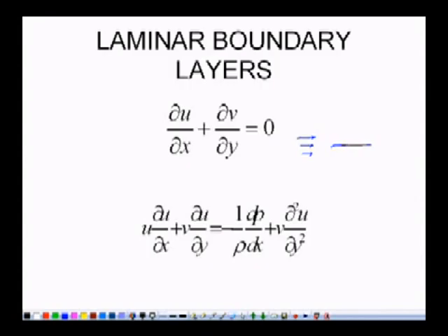right. On this flat plate we want to know what is the force being applied by this fluid which is coming with velocity u to hold this stationary in x direction. We have to apply the force in this direction to keep this plate stationary.